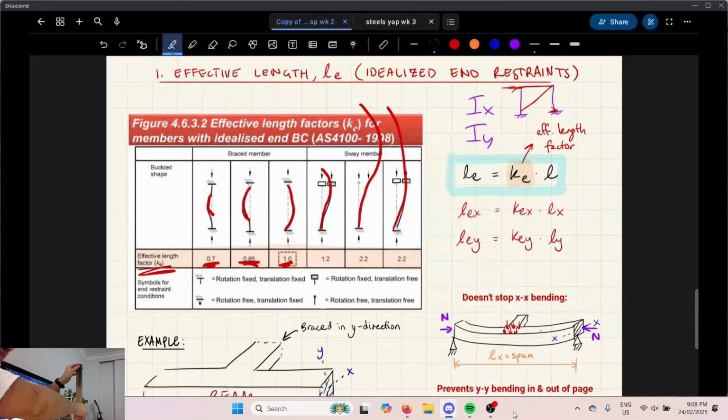That's the major axis. That's fine. But now if I push down, do you see what's happening with the shape? It's 2 buckles. I'm restraining it. Yeah, exactly. It's 2 C's. I'm not sure if the camera can see it very well, but it's like an S basically. It becomes an S. So my hand is restricting it from buckling in the minor axis because it can't really go towards me. Make sense?